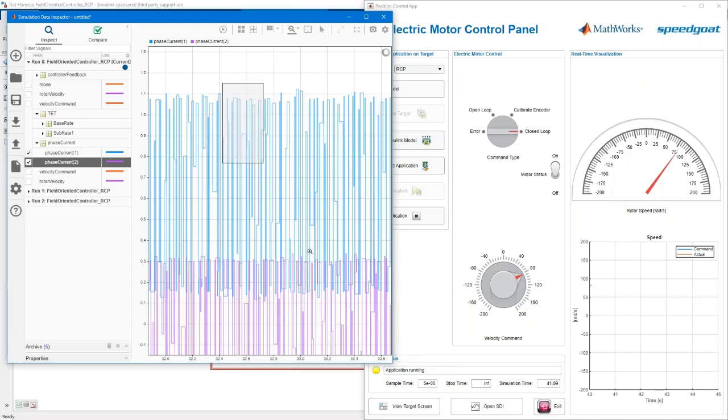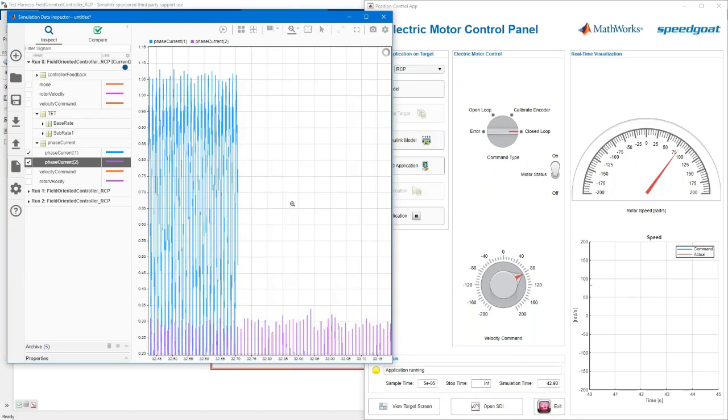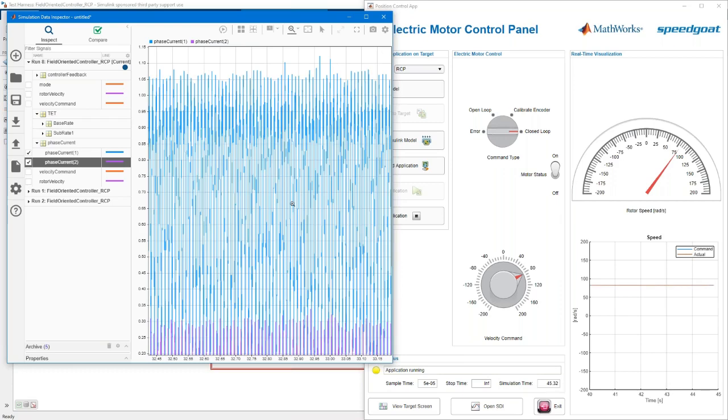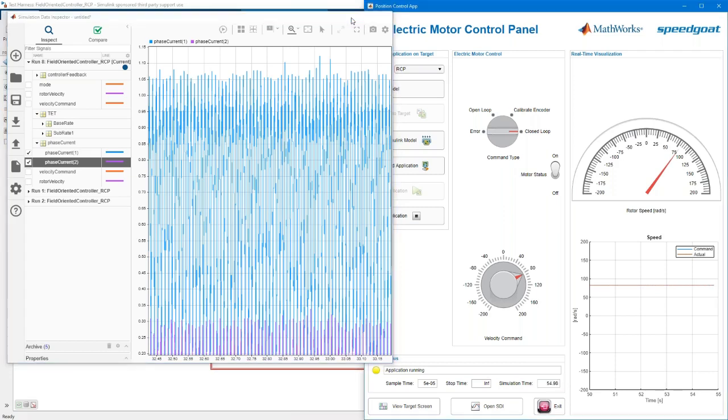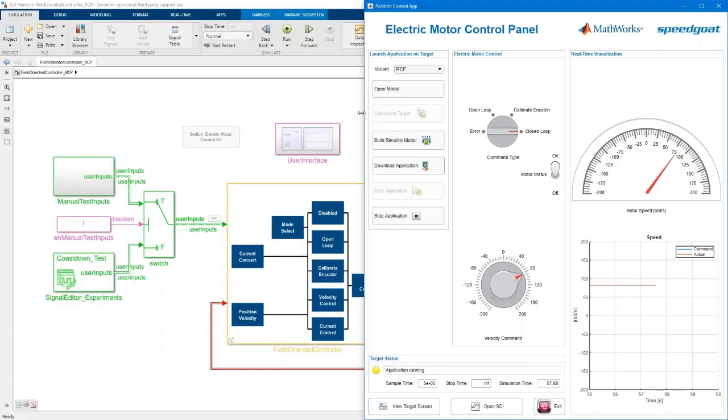If we zoom in a bit more into this signal, we will see why PWM generation from a powerful FPGA model is required, because otherwise a CPU would not be able to cope with the megahertz requirements regarding PWM generation. So this is really a key thing here.